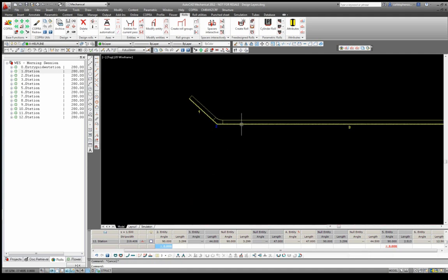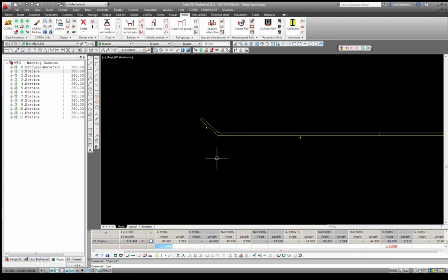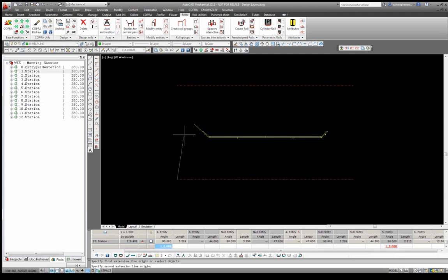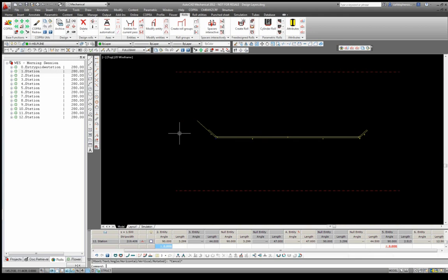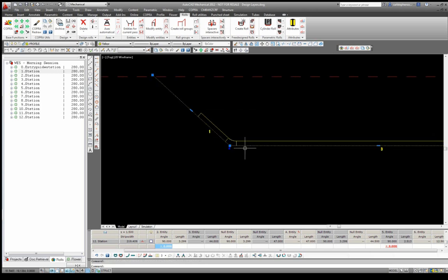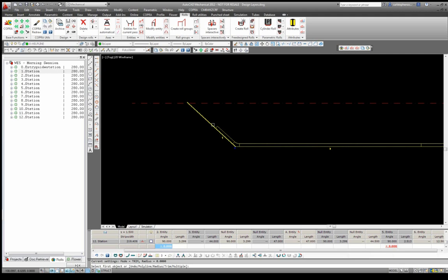I'll increase the length over here in this direction to give me a lead into this first station. Now I'll take a quick dimension from here to here, which will tell me if I offset the bottom line, being the center line, by 94, I should have a nice suitable flange diameter. Now if I take the fillet command, a radius of let's say 8 millimeters, I can first of all select the polyline here to here, and this will now give me my flange and base drive diameter.